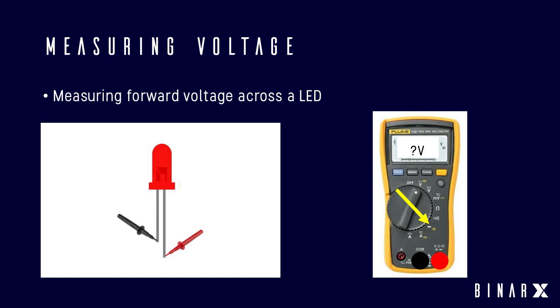Have you written down your numbers? Do we do it at the highest point or the lowest point? Unfortunately, in the real world, components are non-ideal, which means it's anywhere between those two voltages. So I'm going to make it the highest point just to make sure. Yes, that's what you should do. You should always work towards the worst case scenario. In this case, for the forward voltage drop, the lowest voltage is the worst case scenario. So everyone got their right voltages, so everyone's wired up correctly.